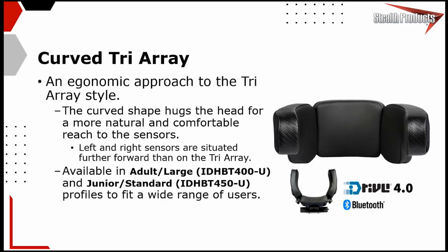So what that means is the curved tri-array, in addition to being a little bit more ergonomic, tends to work a little better for the client who might turn their head side to side to look into the direction where they want the chair to drive, where the standard tri-array might be a little better for somebody who maybe does a little bit of lateral flexion and leans their head side to side to turn the chair rather than rotating their head.